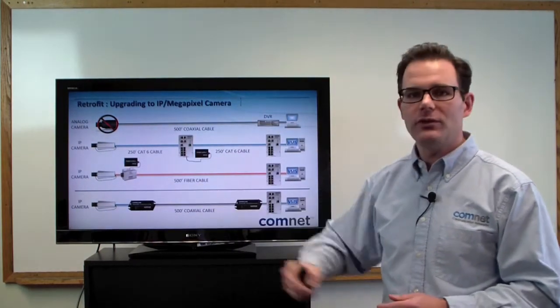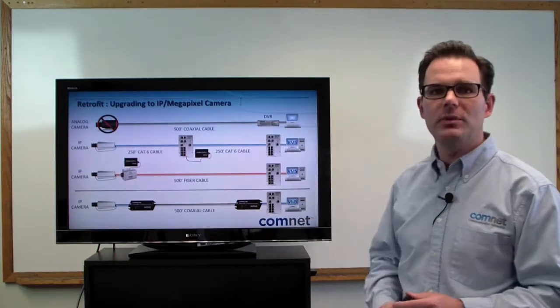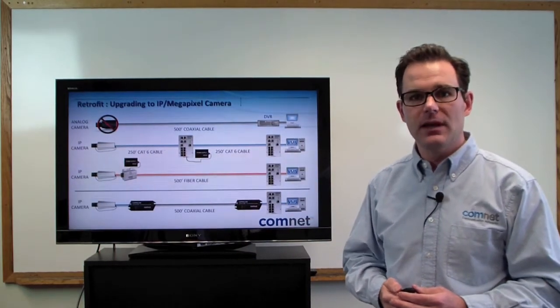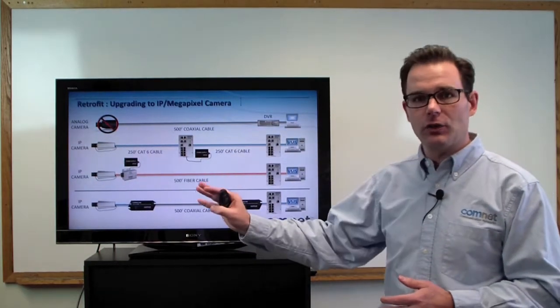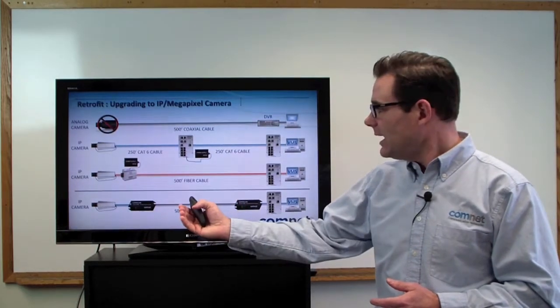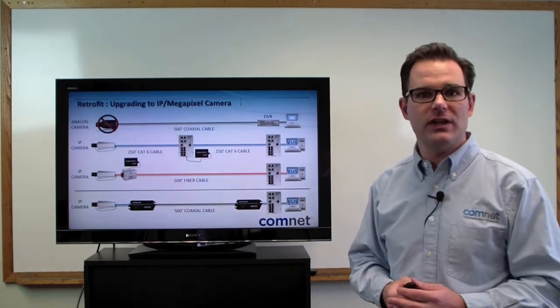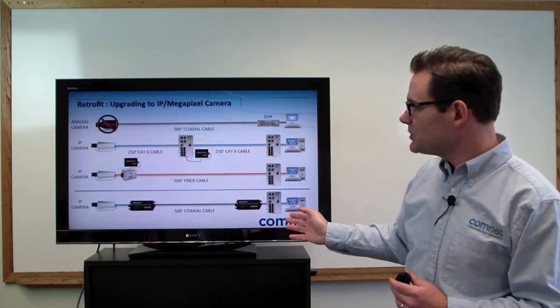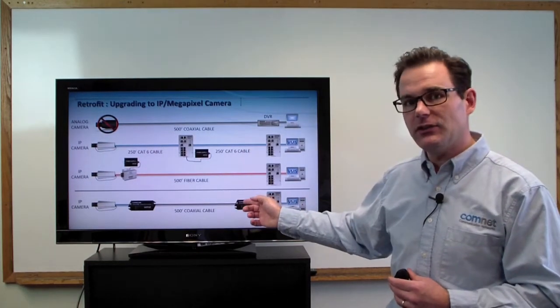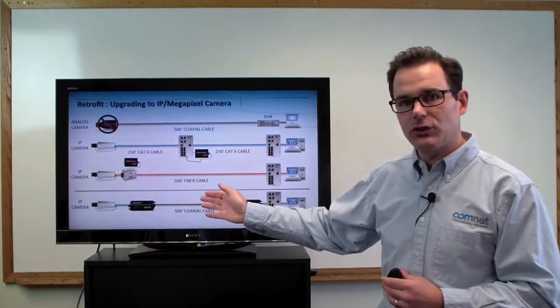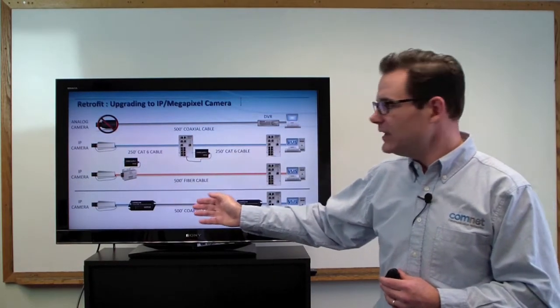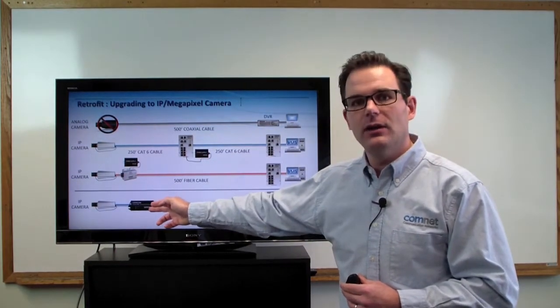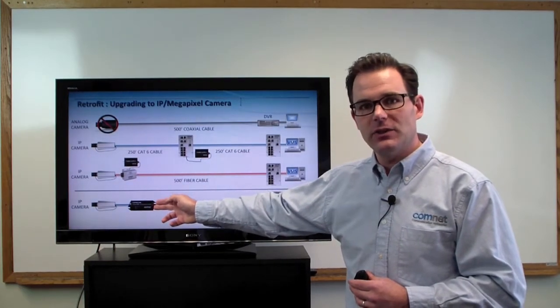All three of those remote devices can be powered with that internal PoE switch. This gives you the ability to remove all external power requirements and cover that distance over the existing cabling. So that satisfies a whole bunch of positives for this installation, meaning you've used the existing cabling, you've removed external power, so really all you've had to do in the field is replace the camera, add the media converter, and connect it to existing cabling.